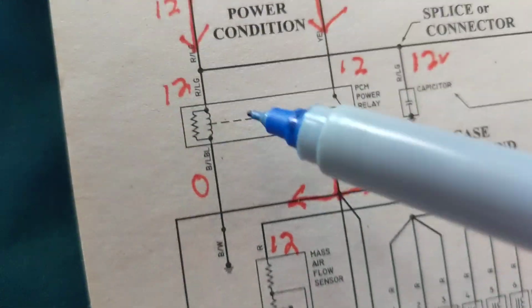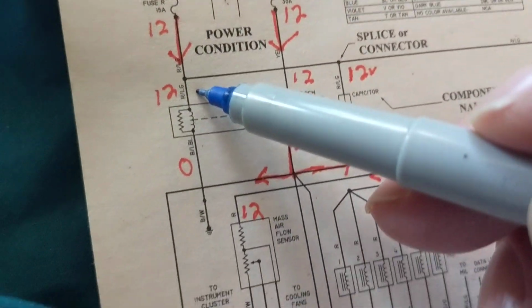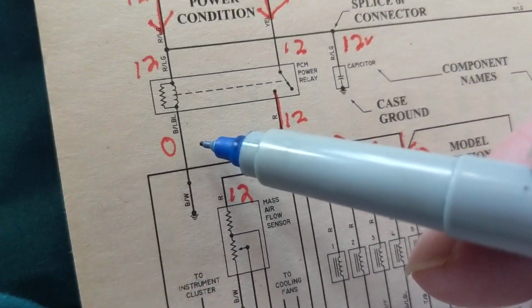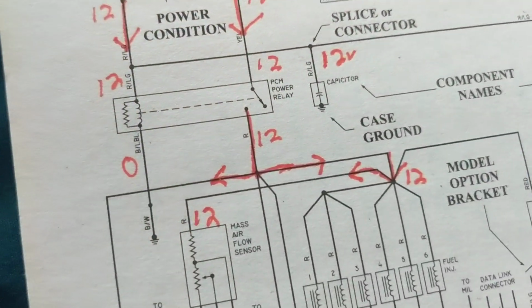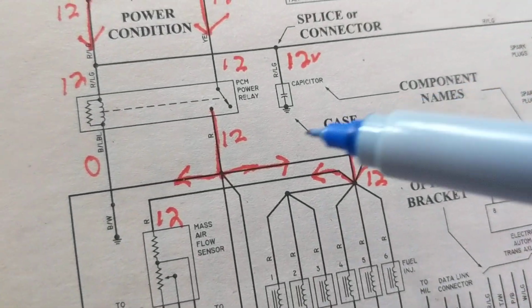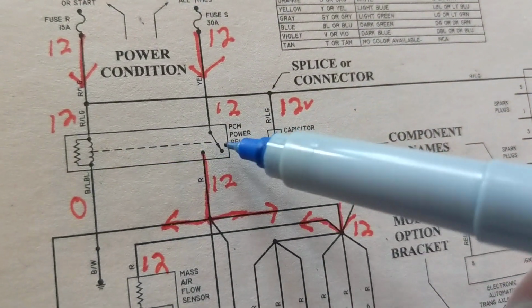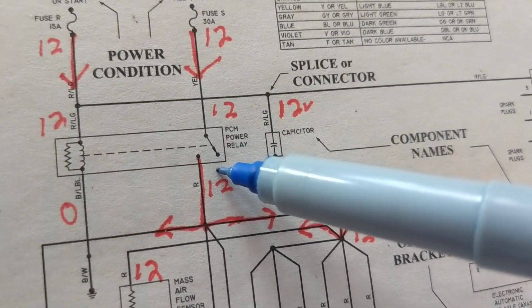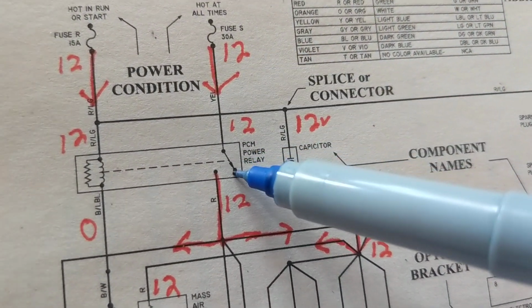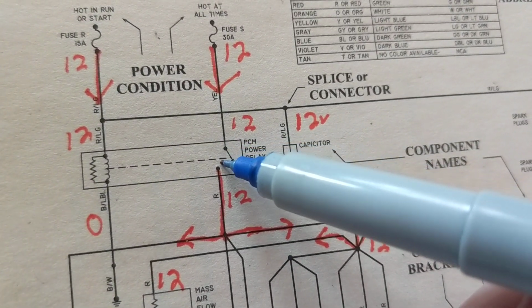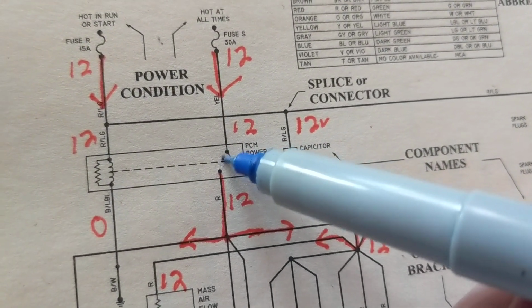Great. Now, 12 volts over here. And if this is ground, how much should be the voltage? 0 volts, always. Always 0 volts if you're connected to ground. That gives us the right for this contact to close. This contact that was normally open will be now in this position.